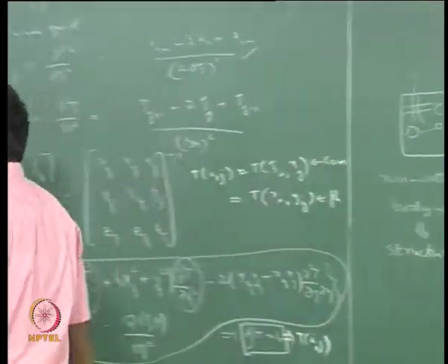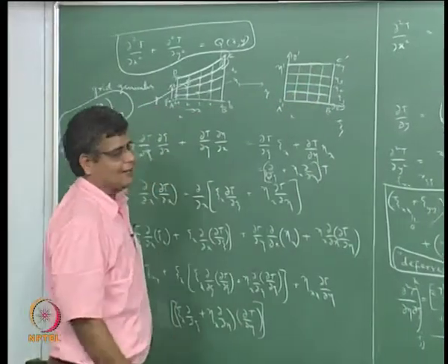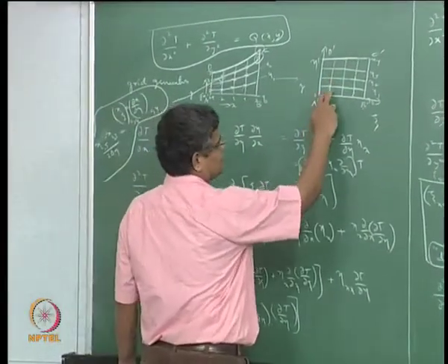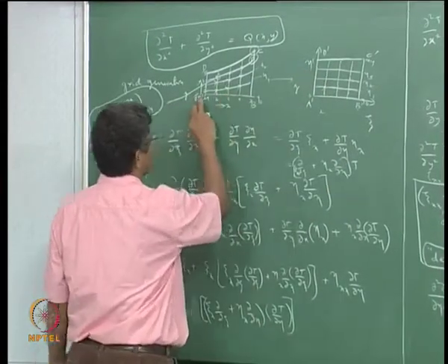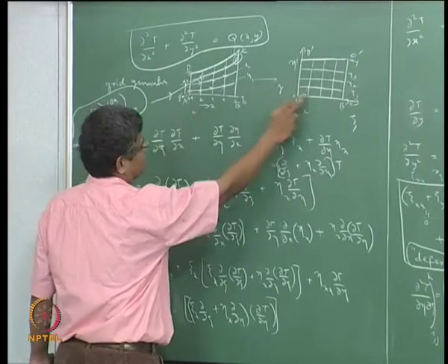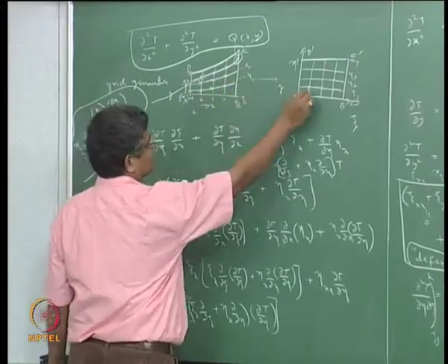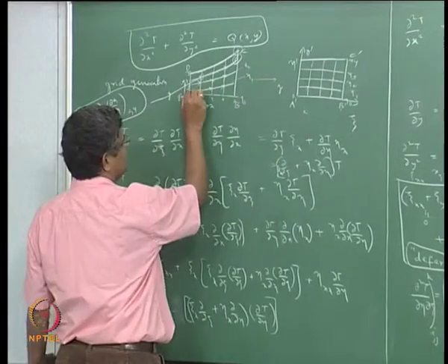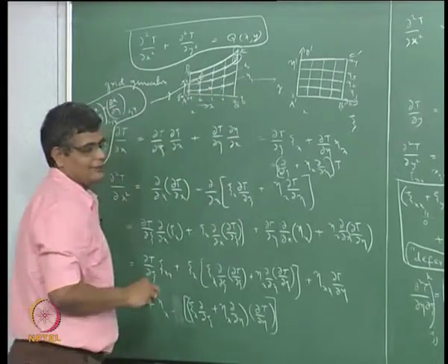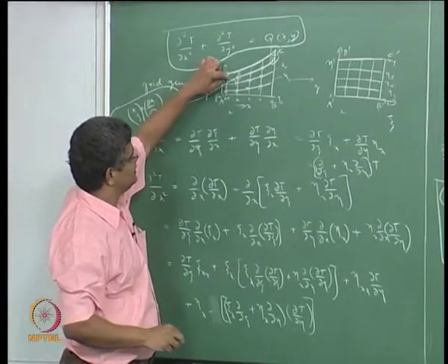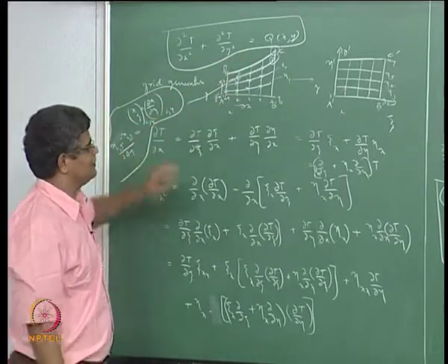And for example, here every point is at an intersection of a constant psi line and a constant eta line. This is also constant. So we are looking at this transformed line here. The corresponding point between this and this is along this constant eta line and this constant psi line. So the grid points here are intersections of the family of lines of constant coordinate directions.